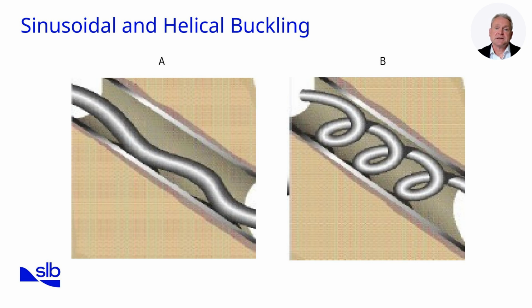When drilling a 6-inch horizontal hole, it is not uncommon to mistake a helical buckling issue for a hole cleaning issue and end up performing a wiper trip. In these situations, you need to slack off the weight and increase the RPM. Understanding this progression is important because it helps us anticipate the consequences of increasing compressive loads.